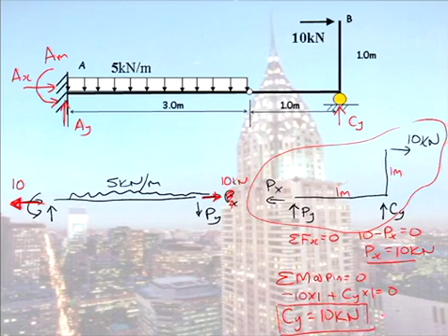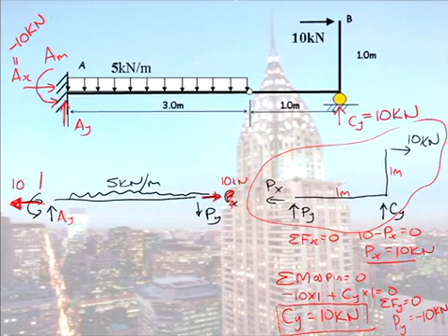And I don't have room here. Oh, well, I'll squash it in. If I now do all the forces in the Y direction, we then have the force at the pin is minus 10 kilonewton. So up here, I'll say we now know CY is equal to 10 kilonewton. And we said this AX value, well, that's equal to minus 10 kilonewton, which means it's going the other way. So we still have the AY to derive and AM, the reaction moment, to derive.